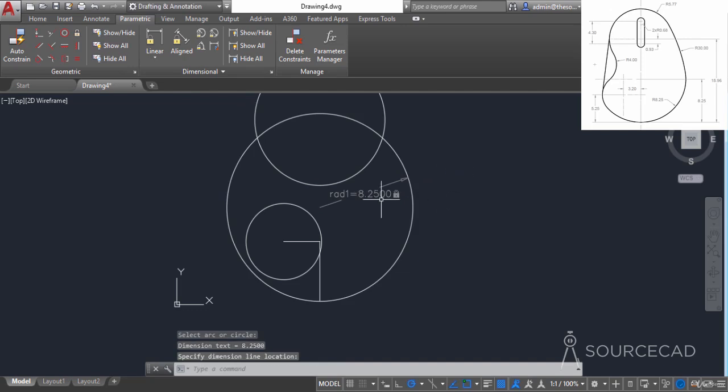Now moving on, I'll select this radius tool, I'll click on this circle, and I'll just click somewhere here, and that will add this constraint. So this lock icon, this padlock icon, actually indicates that now this constraint has been added and the radius cannot change. Now let's add another constraint. I'll go to this fix, click on this circle, and now the center of this circle is fixed. You can see that the padlock icon has been added.